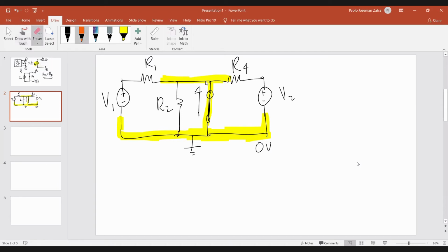So how do you solve for IN in LTspice? You can't actually measure the short circuit current in LTspice, but we can approximate. Instead of just putting a shorted line here, we can place a resistor, and you set its value to 0.000001 ohms, so that its resistance is almost negligible.